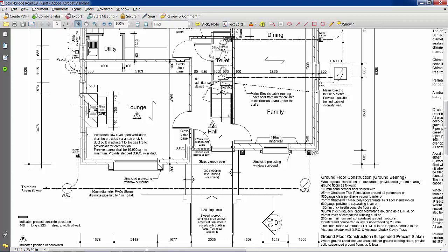So typically, as I said, a rainwater pipe could be 83mm diameter, and your gully trap there something like 200 by 200, and then you need to check that you have the likes of this access joint here with the right diameter. So that one looks as if it's possibly 400mm in diameter. These are preformed plastic systems that can connect together to accommodate different heights with a little manhole point on top.